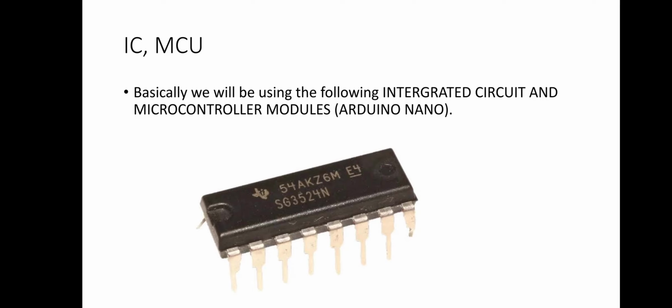which is Arduino specifically. Now you can see beneath, SG3524. SG3524. Now this IC is an analog IC. It provides a square wave signal, though, but I will teach you how to modify this square wave signal to a modified sine wave signal and lower the noise coming from this IC.